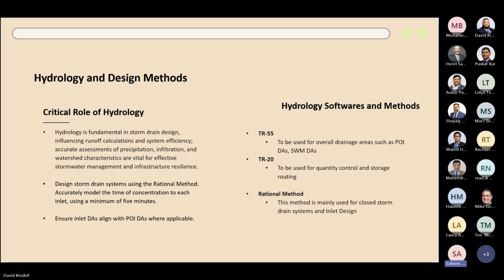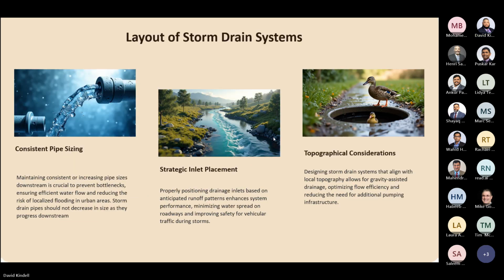TR20, I think we have had a good discussion, and it is more complex. If we have to design a pond or route the water through a pond within our drainage system, TR20 is more appropriate. Yeah. David, you can go on.